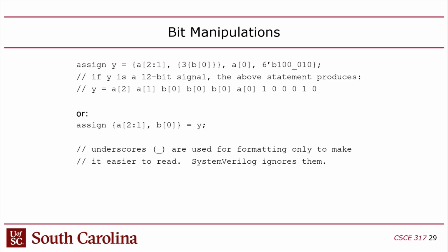If the PWM frequency is low enough, it'll still work, but you'll get flickering. Whereas if it's fast enough, I think the LED's capacitance will smooth that out. I don't know the answer because I don't have a model of the LEDs on the board.